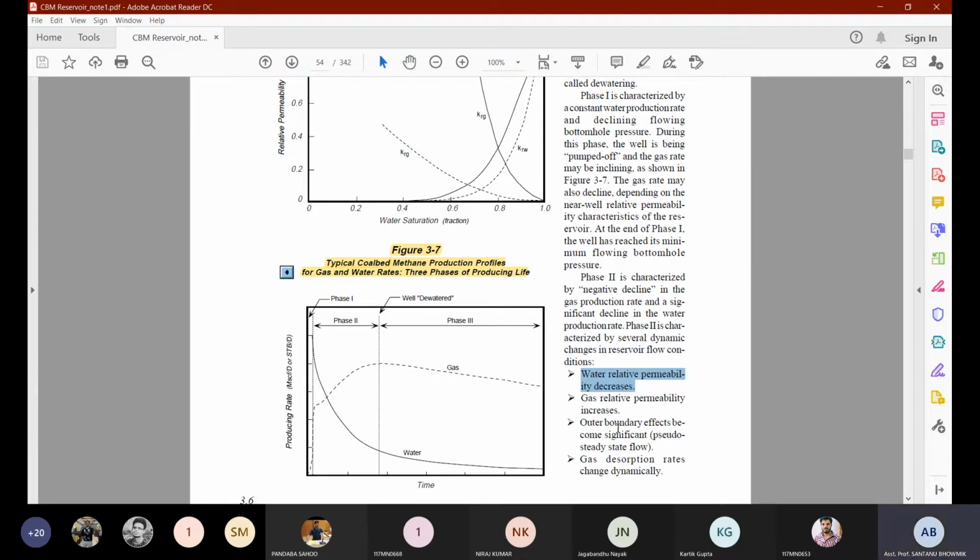If the fractures are connected, it is totally connecting the gases from all the reservoir, and then they are going to diffuse, they are coming to the natural fracture systems, in the free state, and from this free state, as the pump is working, it is creating negative suction pressure. So the total amount of gases from the fractured zone is going to move to the surface through the borehole.